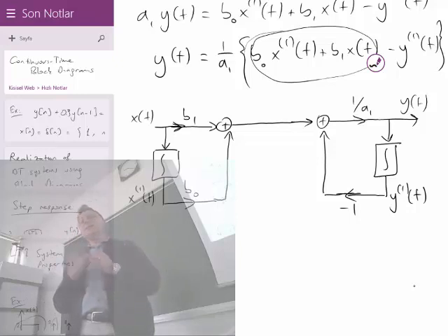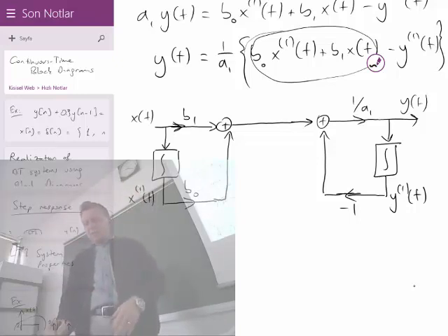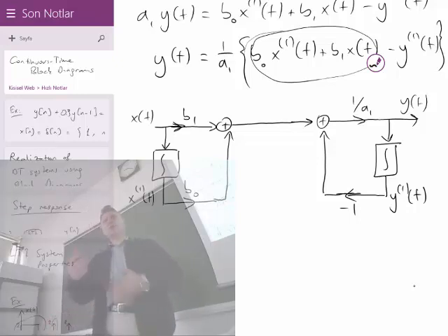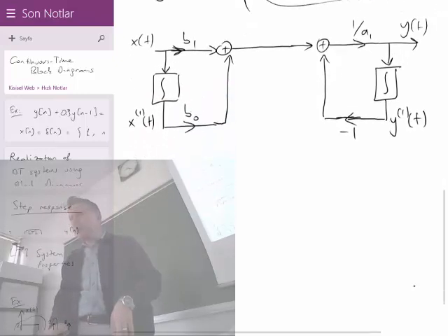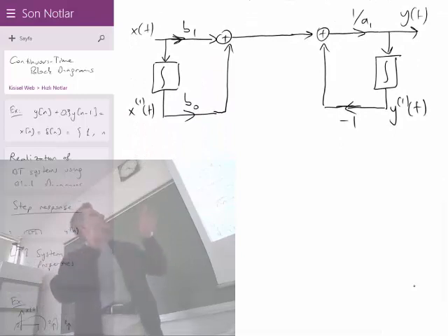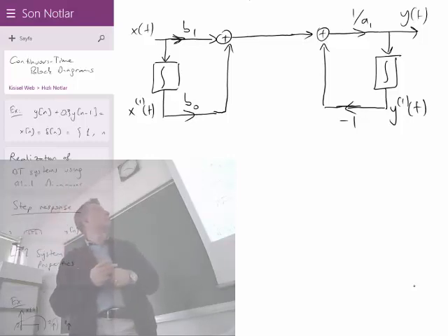Why did we shuffle the order? Because we didn't consider the differential equation, we just inverted it to an integral equation. So all the orders have changed. If you use derivative operators here, then it would be B0 first and B1 next. But since it is an integration, the order has changed. And then, how do we get rid of one of the integrators? Again, the similar trick. We will interchange the places of these two. And when we do that, two integrals will correspond to the same operators, so we can merge them into a single integrator in the center, just like we did for the delay operator combination.